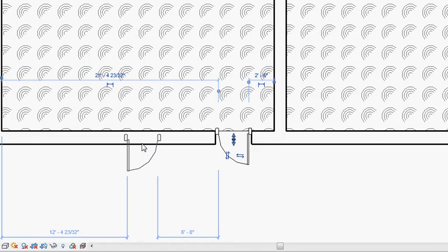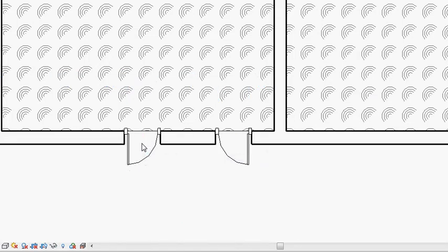And one thing nice about everything being parametric, it's fully parametric. Things can slide and move and shift without you having to redraw or actually touching the model itself. As long as the parametric is correct, you cause fewer errors. The more times you touch the model, the more errors you can inflict on Revit, which can actually lock up and freeze things. And you don't always want that with Revit, especially when the deadline is Friday at 12 o'clock and everything locks up.